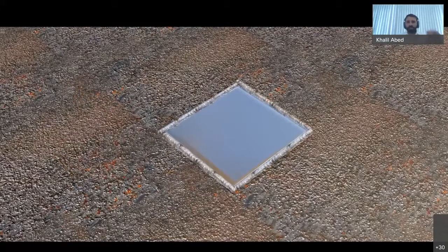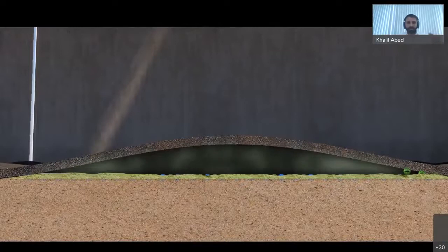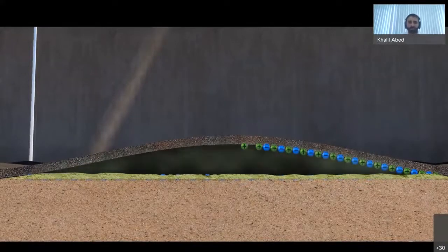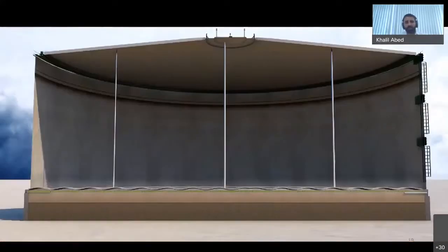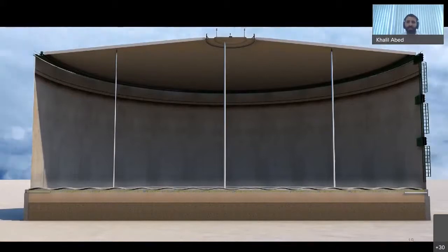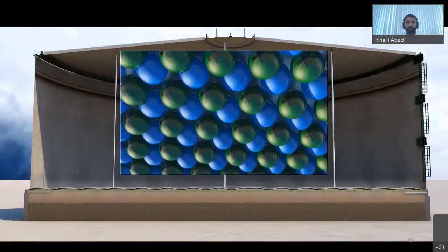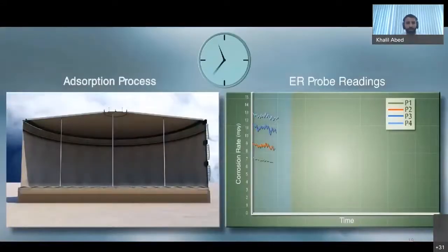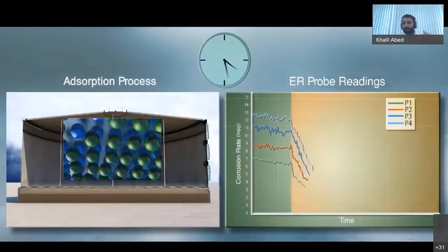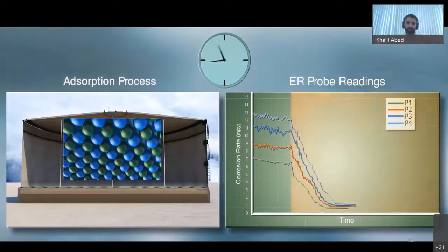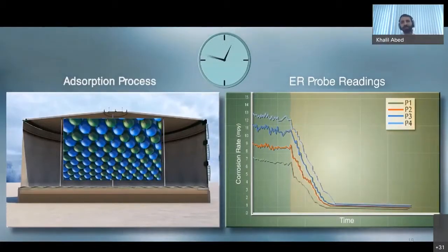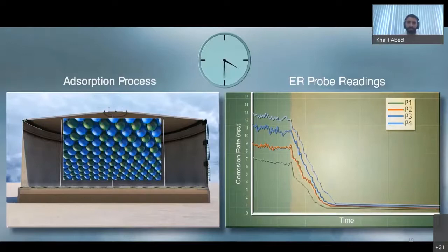Once the powder is trapped under the tank floor, it starts to sublimate, and then it releases the protective molecules and provides protection against soil side corrosion and suppresses the active corrosion rate on the tank floor. And with the use of the corrosion monitoring probes, you can see the effect and the reduction in the corrosion rate with time.